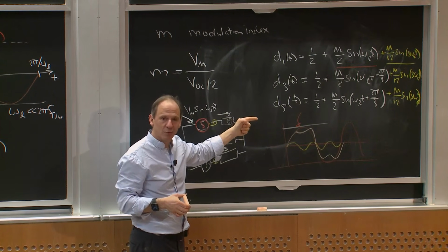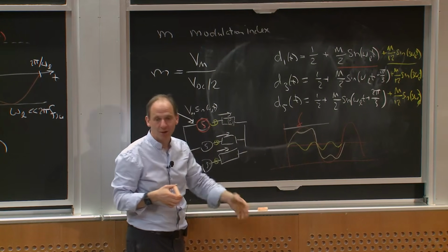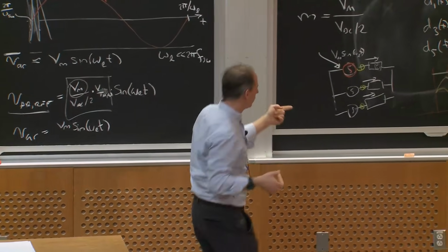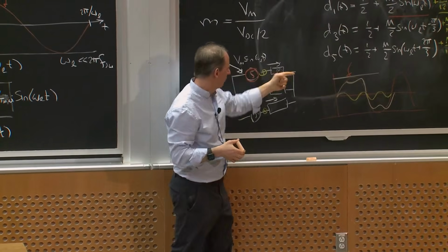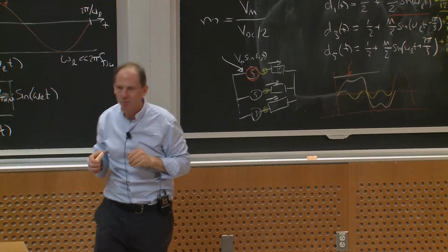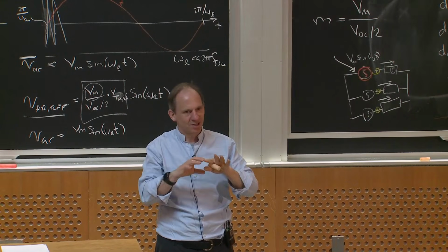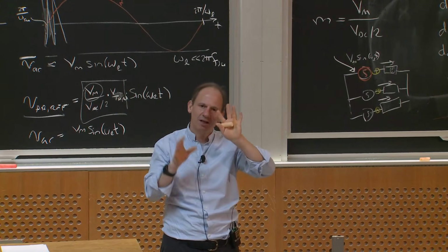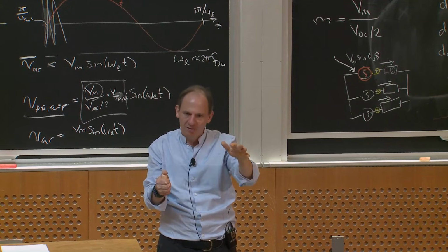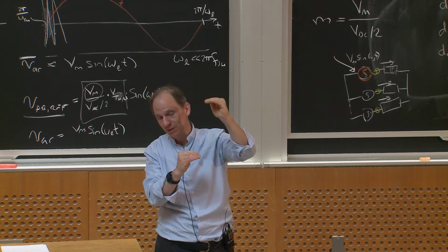The only problem with doing that is that the waveform has a third harmonic, which will cancel, but it also has 5th and 7th and 11th and 13th, and I will get harmonic currents flowing in these phase windings that probably aren't helping me drive the machine. So I can synthesize nice sine waves, at least on a local average basis over a switching cycle, until the amplitude equals VDC over 2.